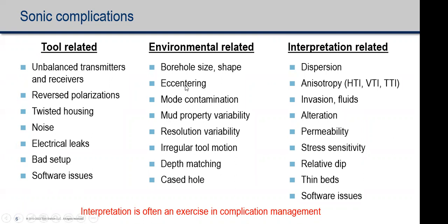I think it happens quite often, not so much in vertical wells, although you see the effects of what I think is excentering. It's especially a problem in horizontal wells. Another complication is we're not measuring the velocity of the mud. And it varies; drillers often put an 18-pound per gallon pill at the bottom of the hole, and the log header says the weight of the mud is 14 pounds per gallon.